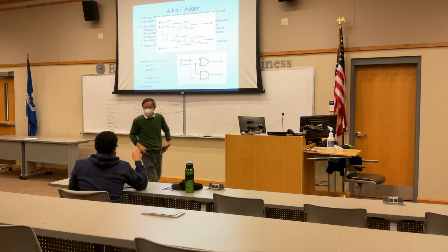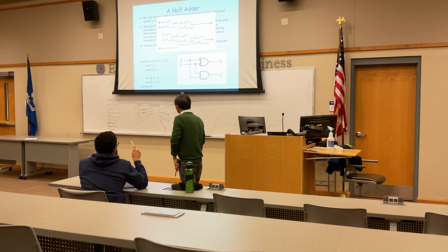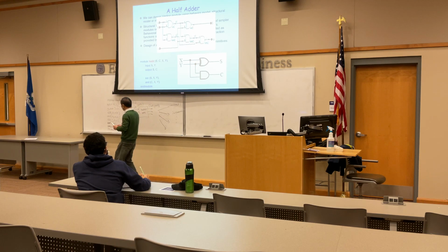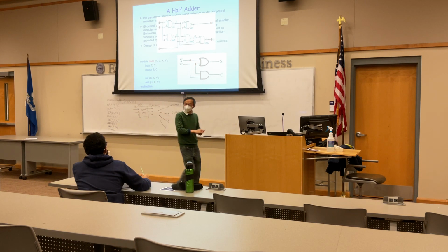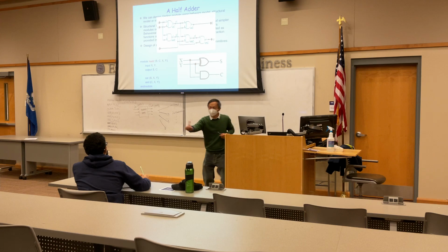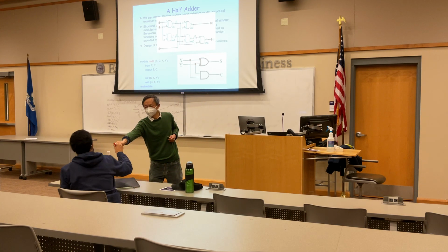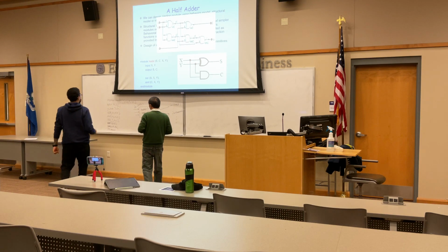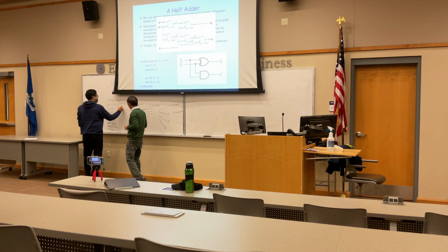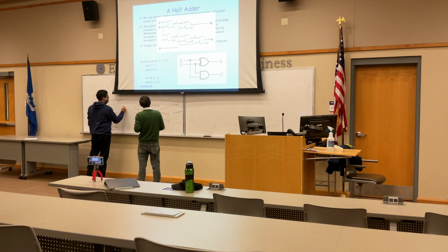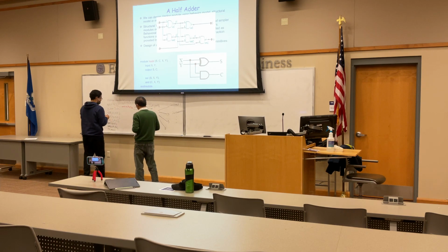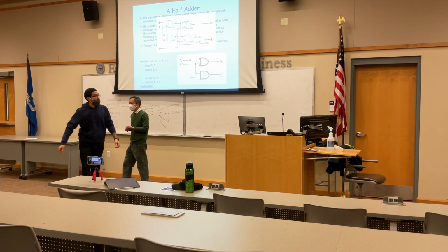I hope everybody has your own code. His question: do we have to declare a wire? Oh yeah, we do need to declare wires as well. So we need to add another line. Can you add that wire? Because every signal has to be declared before you use it. So we add one more line, wire N1, N2, and N3. Very nice. Good job. Congratulations. Then together, it's a complete code.